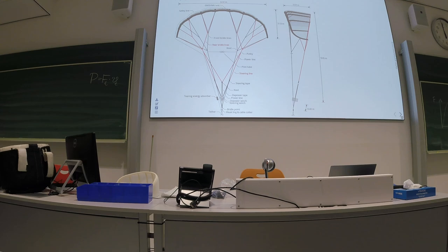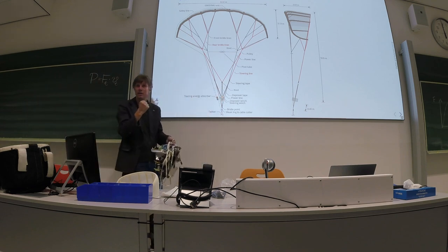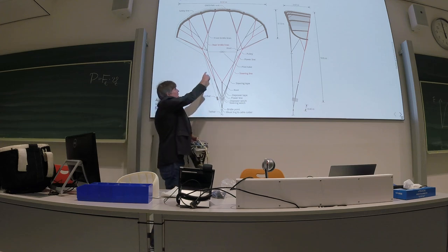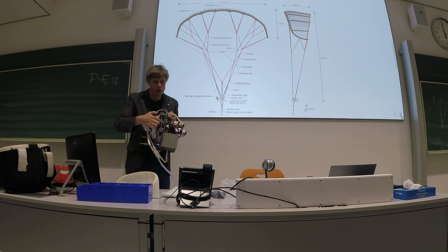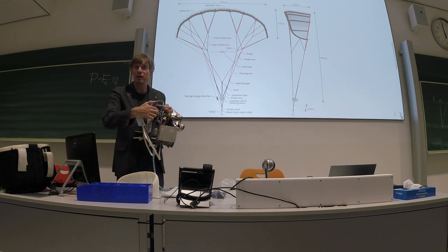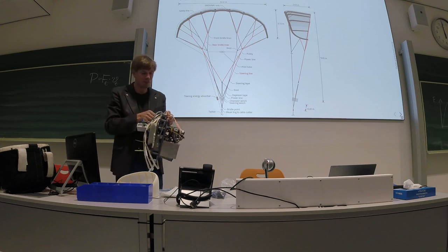You can imagine for the power tape, you need to pull at all times. You see that from this setup, the power tape you need to keep at all times under tension, while the steering lines coming in here, running onto the two mechanically linked drums, only require differential torque to be moved.